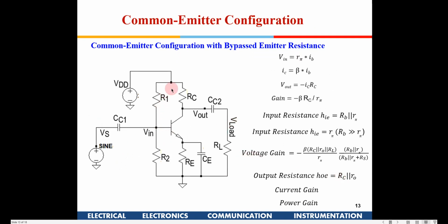Now if you want stable DC operating points but also high AC gain, this is a very widely used circuit, known as the common-emitter amplifier, and it has large applications. Even a similar circuit in CMOS technology, known as the common source amplifier, is used in most state of the art op amps.